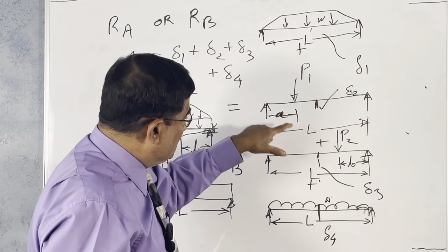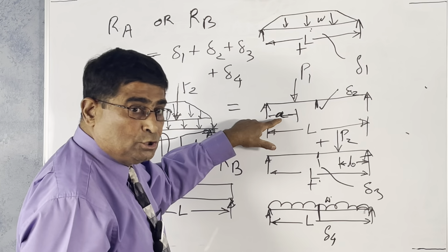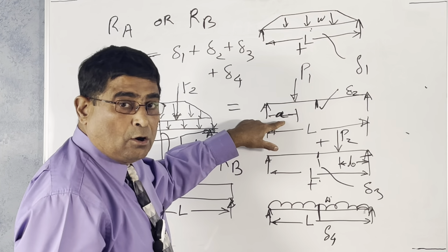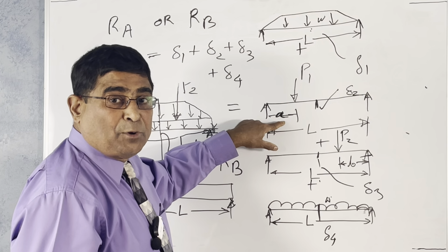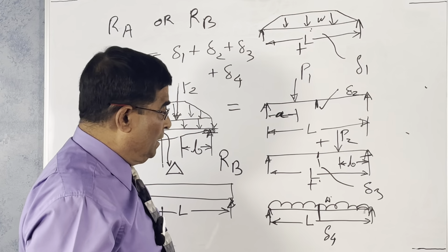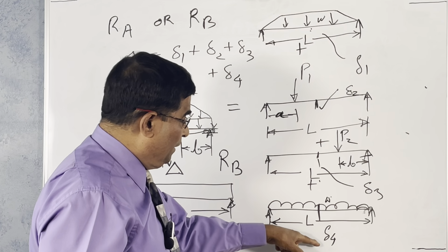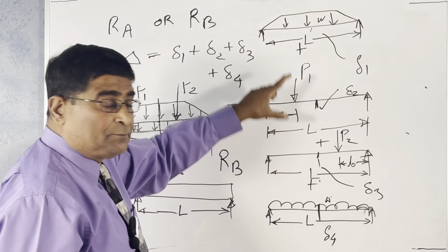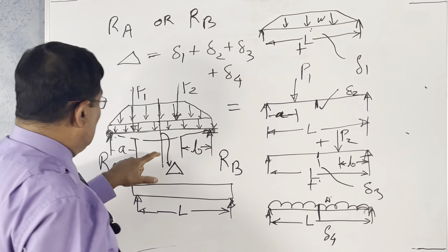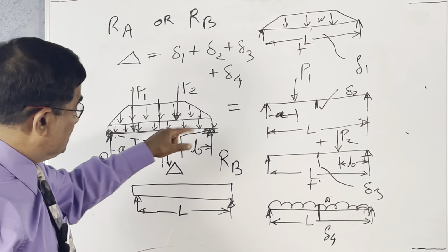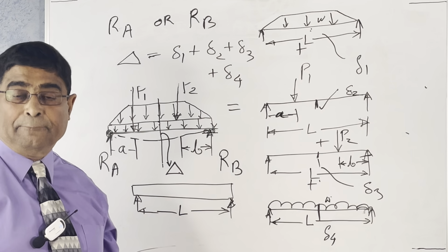You can calculate this by replacing the values you have. Suppose it is 2 meters or 6.5 feet, you can put those values. Similarly here, all these deflections you get from the standard table, and add up, you will find the deflection of complex beams, complex loading systems.